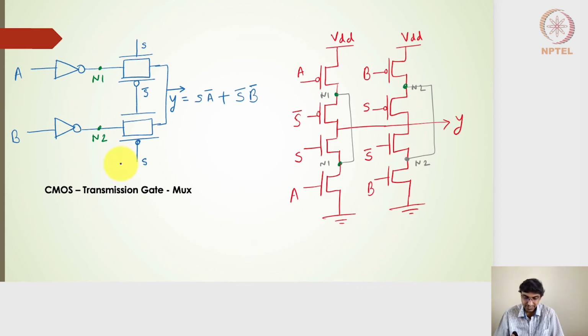So the transmission gate multiplexer and the tri-state multiplexer, the schematics I have designed, we notice that the stick diagram is different by only one metal contact. So if I actually connect the schematic with this N1 and N2 connection, this behaves very, very similar to that of the CMOS transmission gate designed multiplexers.